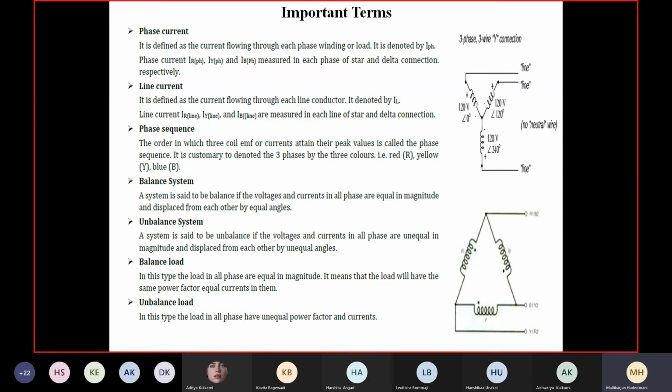The other is load. When it is a generator, I can think of this. If it is a load absorbing the power, I can say the same thing. Balanced load means the load is absorbing equal power in phase R, phase Y, phase B. The load is drawing the power in all its arms in a balanced way. Unbalanced: for example, the R group is heavily loaded, Y is lightly loaded, and B is most probably not loaded.